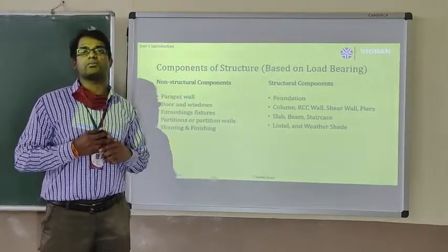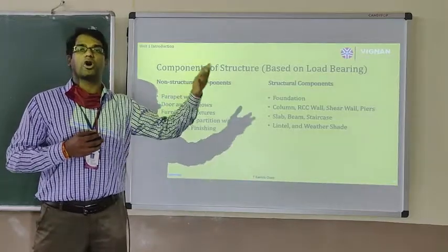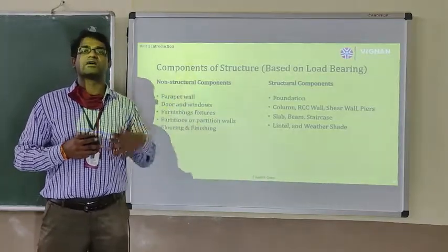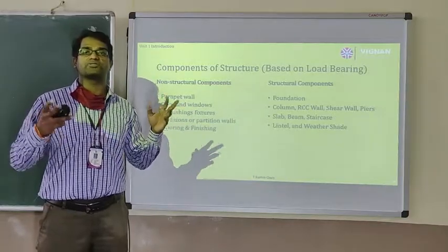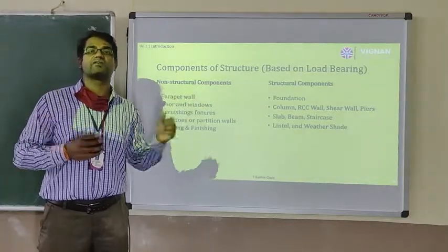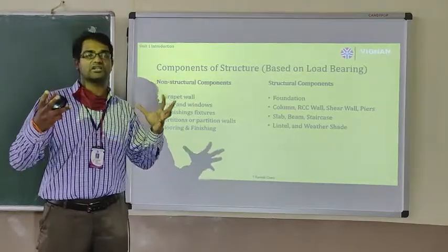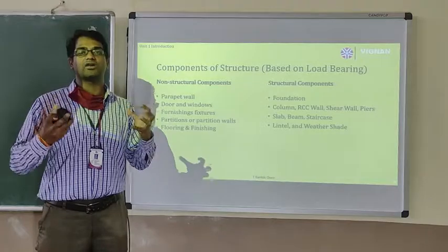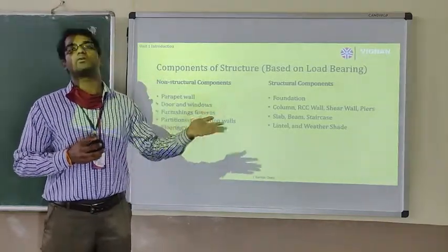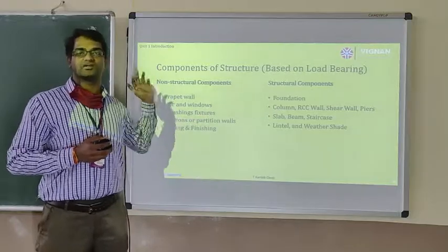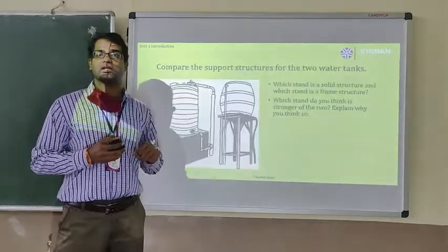When it comes to structural components, your foremost thing is the foundation. Second, the columns, RCC walls, shear walls, piers, slabs, beams, staircases, lintels, weather shades. These all come under structural components, which essentially carry all the loads and transmit them to the foundations. So based upon load bearing, there are non-structural components and structural components.